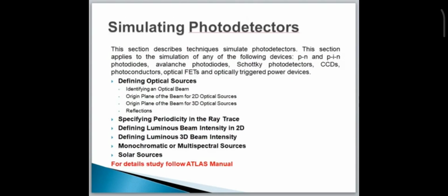The next slide will explain simulating photo detectors. It will be used in PIN diodes, LEDs, organic FETs. This section describes techniques to simulate photo detectors. This section applies to the simulation of any of the following devices: PN, PIN, photodiode, avalanche photodiode, Schottky photodetector, CCDs, photoconductors, optical thyristors, and optical triggered power devices,